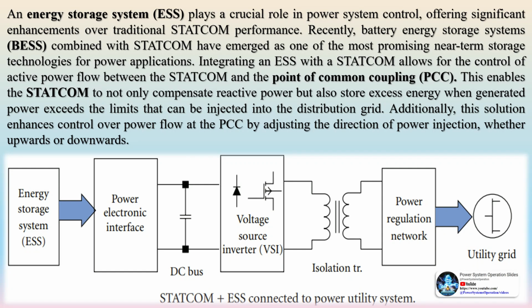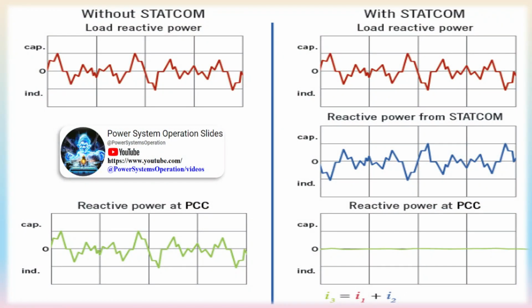The number of steady-state operating modes is extended to include inductive mode with DC charge and discharge, and capacitive mode with DC charge and discharge. Thus, the STATCOM plus BESS can operate at any point within the steady-state characteristic circle. Depending on the energy output of the battery or other ESS, the discharge charge profile is generally sufficient to stabilize power regulation in the system and maintain operation until other long-term energy sources are activated. Figures show the architecture of connecting BESS with STATCOM and the control architecture.